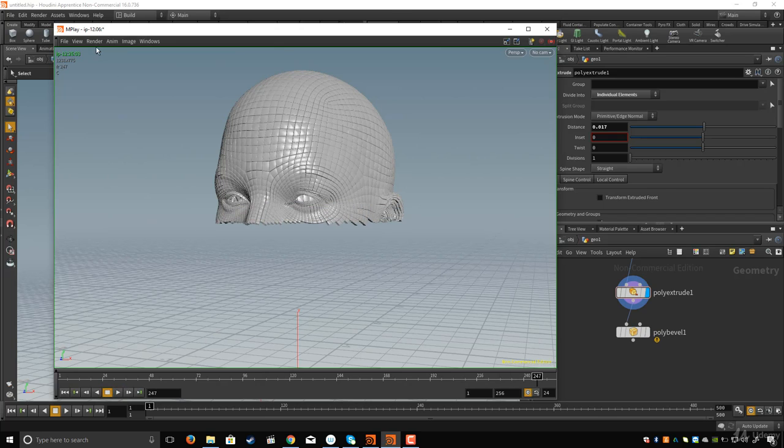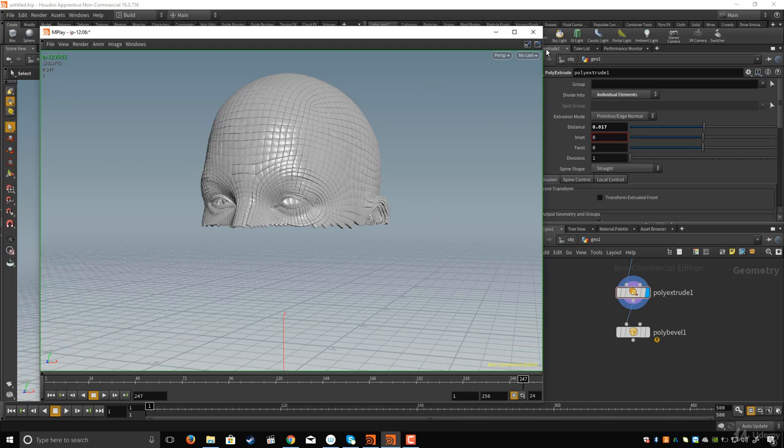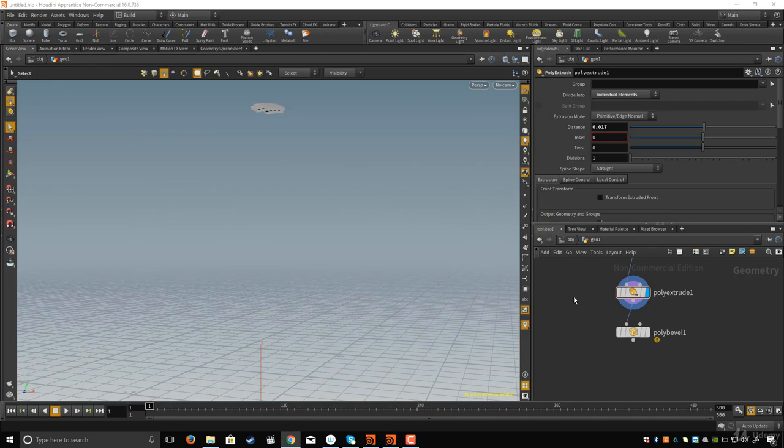Let's come here to the render and click on disconnected. What this does guys, if you create another flipbook, this will not be overwritten. This will be independent. I will minimize that, and now I will delete the poly bevel, or shake it and put it aside here.